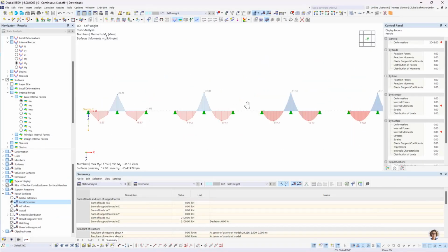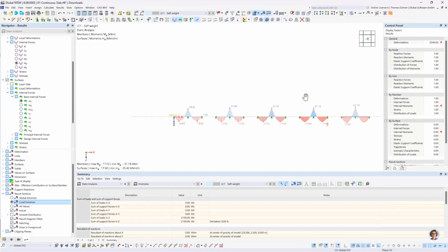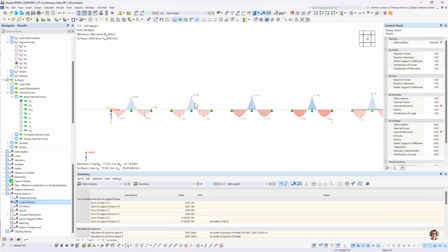So here, maybe we can look at that quite a bit better. Here this 28.45 versus the 31.818. Yeah, almost 10%. That's not quite good. So that's the problem with this coarse mesh. We will lose exactness in the results.